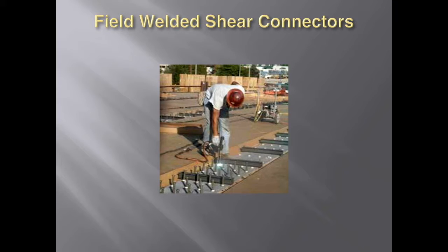We've gone through several decks where the guys haven't broke off the ferrules. They've basically just put 1,000 studs in along the top of that girder and not broke the ferrules off. But walking across the deck, you happen to catch your foot on one of those studs and it just pops off, which is a bad thing. They're not supposed to break off that easy. So you start breaking off the ferrules, knocking them off, and you go through the whole thing and find out that I think there were 500 studs that weren't welded completely. So they had to go through and break them all off and reinstall them. And unfortunately, they had to wait to get the studs in because they didn't have any at the local hardware store. They had to order them in.